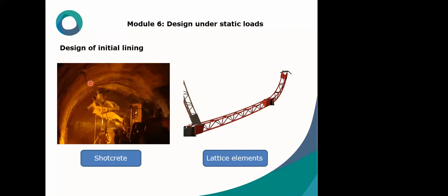Here in this picture, you can see the lattice installed in the tunnel and the shotcrete covering it. These have been developed for special demands in the field of tunneling. This system has been evaluated and employed very well all around the world, and the lattices provide immediate support in an open span area. These elements are integrated in the shotcrete.